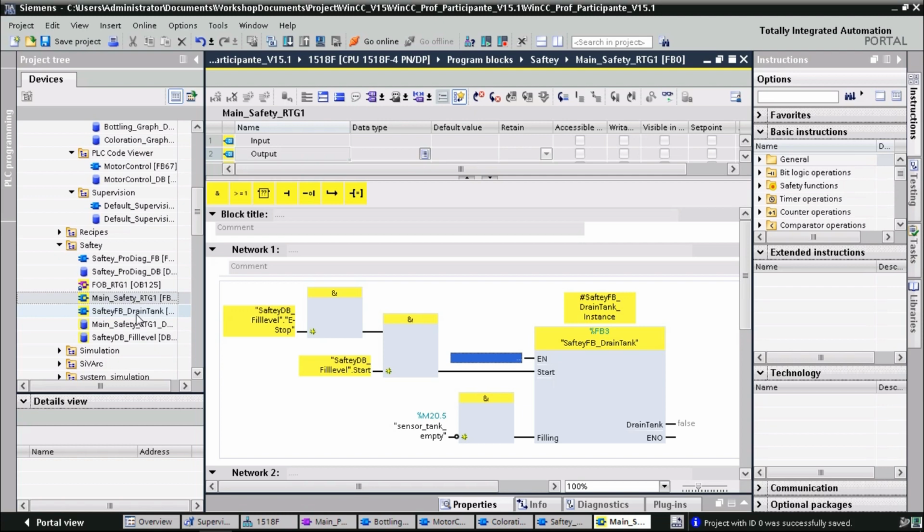So just more information. You also have new events in here because of the buttons you have. One of them is again alarm view button click, and the other one is PLC code view button click. So we define here in which screen the PLC code viewer is located, and we do a screen change. Okay.